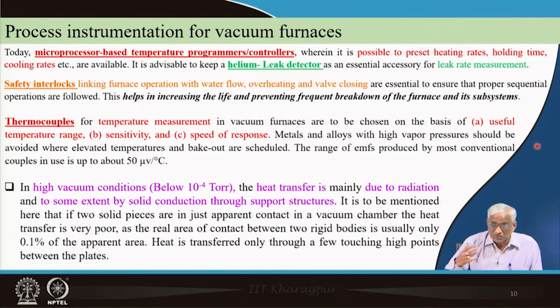And associated with all that, uniform heating. Initially when you switch on the heater, the heating rate may be very high, sometimes it gives trouble, because of huge temperature differences from the heating element to the job. So, radiation can be very high, but you should reduce the electrical power at that time, so that you get a uniform heating zone. There are very good programmable power supplies available.